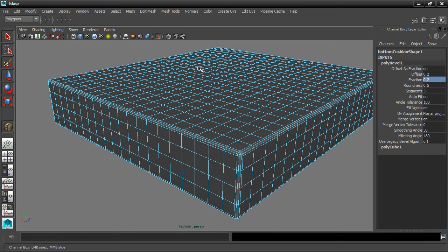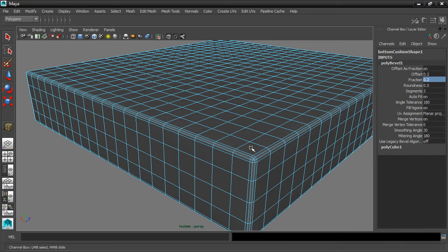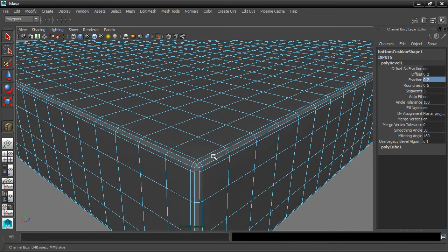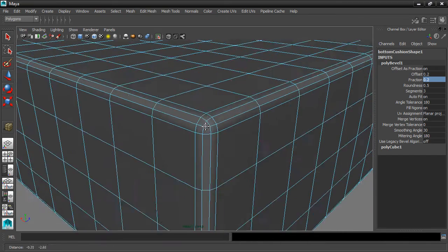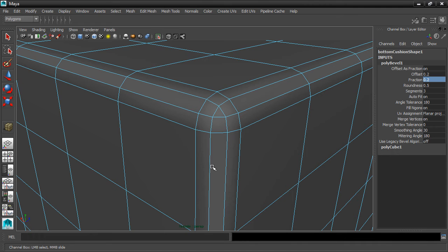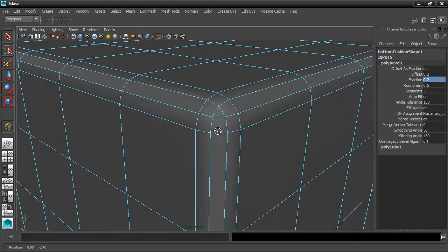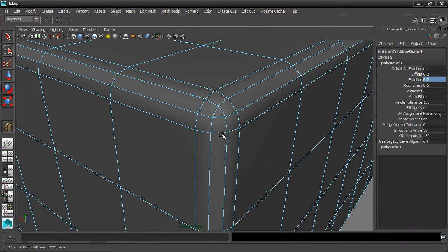I haven't dealt with the overall poofiness or stuffed character of this. I'm actually going to do that last. I'm going to sort out the sort of boxy aspects of this first. What we'd like to do here is add a bead. And to do that, we can do some extrusions on this surface. But you'll notice at these extreme corners where 3 edge loops meet, we have a triangle. And that structure is going to be problematic for us when we do our extrude.